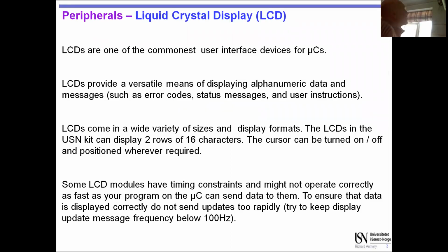I think it's fair to say that the liquid crystal display is in almost every microcontroller application. Very large numbers of them have these displays, and they're so much better than LEDs for actual information. So again, you have to make choices of what is the appropriate way to display data. Sometimes an LED that is on or just flashing, at high speed or low speed, can do a lot. With two different LED colors, you can do a lot of information. You can have one flashing, one on, the other flashing, both just on, one flashing fast, one flashing slow. So you can do so many data signals with just 2 LEDs. Even with 3 or 4, you can do massive things.